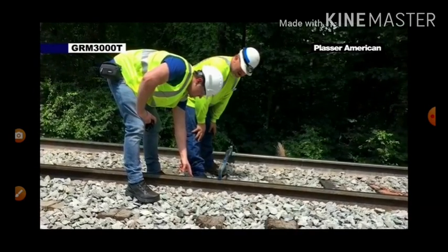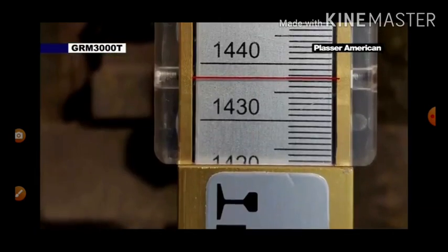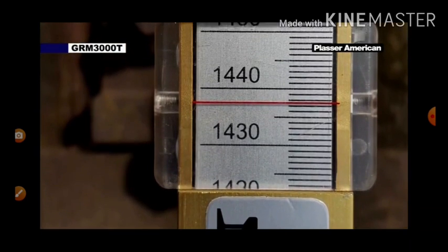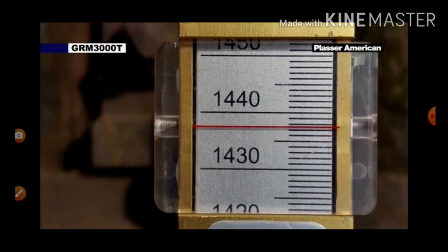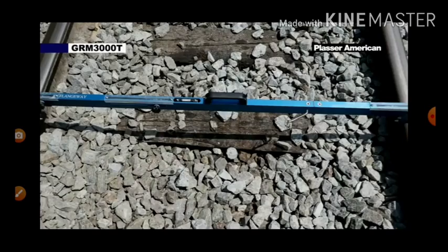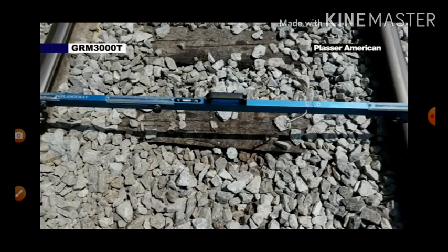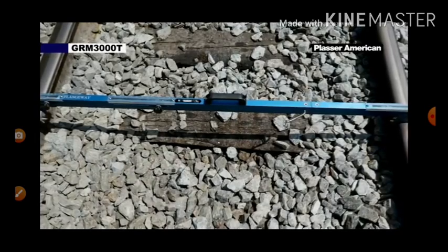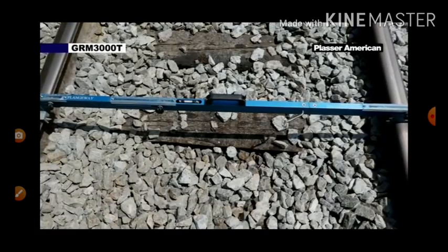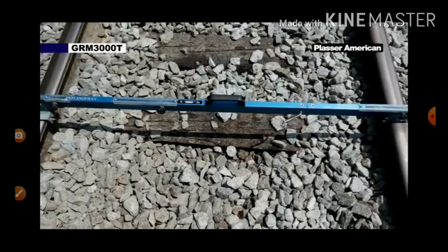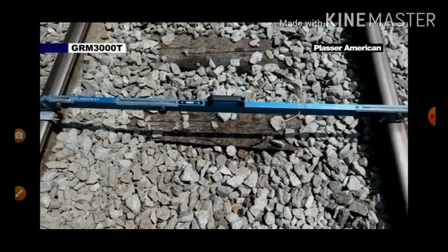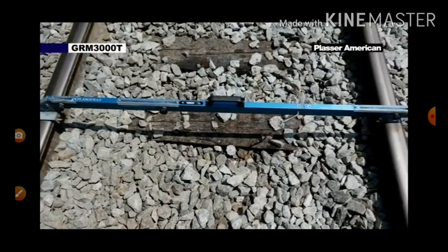The standard track gauge, the distance between two rails, is 4 feet 8.5 inches or 1,435 millimeters. But many other gauges, wider and narrower than this, are in use around the world. Gauge is often intentionally widened slightly on curved track. Gauge is, however, not a parameter the tamping machine can actively modify.